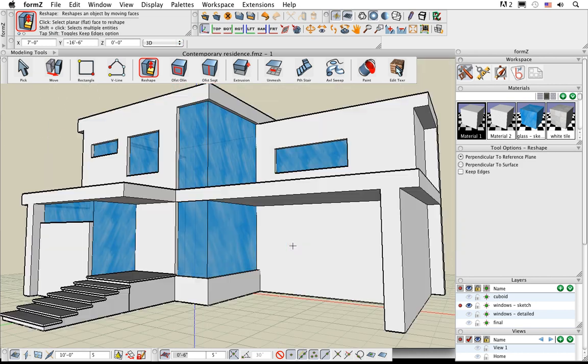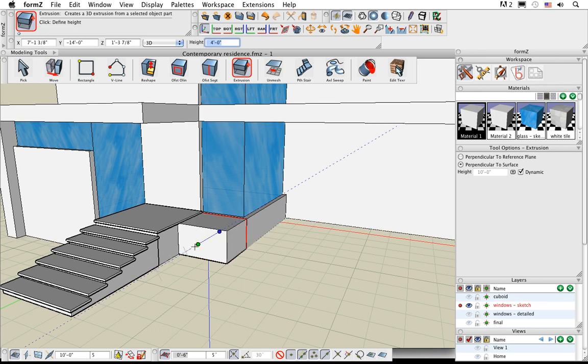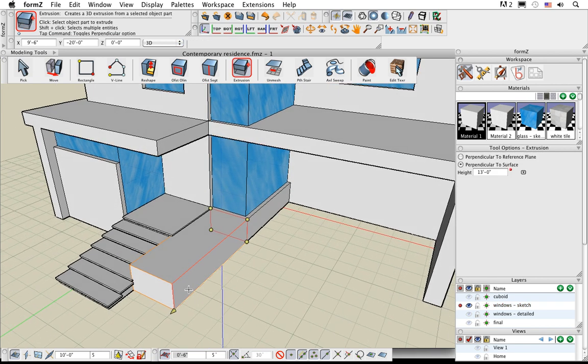I'll tell you what, let's look at it from our front view here, and we're going to put a little water garden in this area as you're walking up to the front entrance of our house. Use the 3D derivative tool again. I'll just simply click on this boundary over here and drag that out to create a new object. So I know that object matches that existing boundary that I derived it from. And that looks pretty good, fills in that space pretty good.